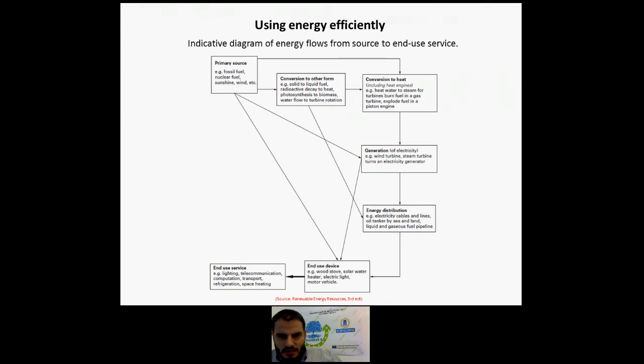Practically, we could say it is often about 35% for coal and nuclear power stations, and commonly less for biomass combustion and geothermal power stations, and most vehicle engines. The largest energy output is therefore not useful work, for example as shaft power for electricity generators, but the waste heat in the exhaust or cooling tower. Of course, if the output heat can itself be used beneficially, it is no longer waste, and the overall efficiency should be improved considerably.